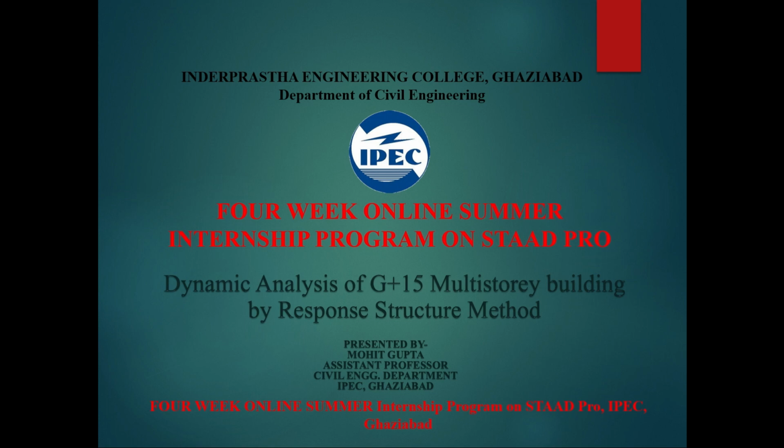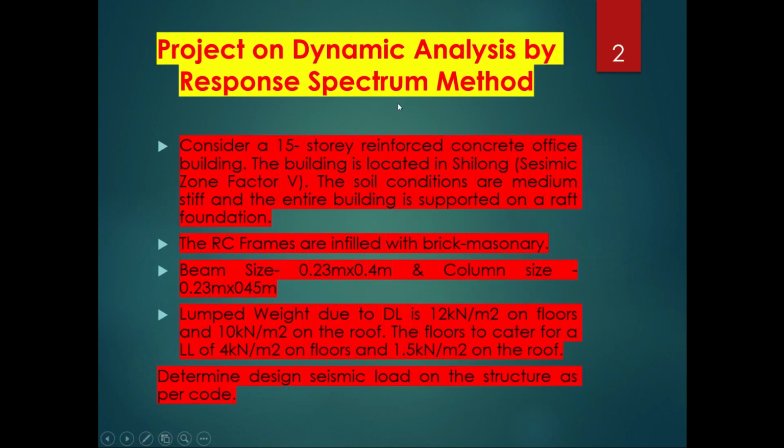So for the G plus 15 building, we have a problem like this. This is a project. Consider a 15-story reinforced concrete office building located in Shillong. The seismic zone factor of Shillong is 5; Shillong belongs to zone 5. The soil conditions are medium stiff, so this is a condition that we have to enter as medium stiff in StaadPro, and the entire building is supported on a raft foundation.